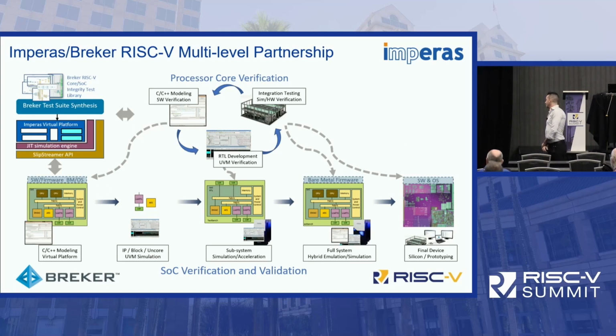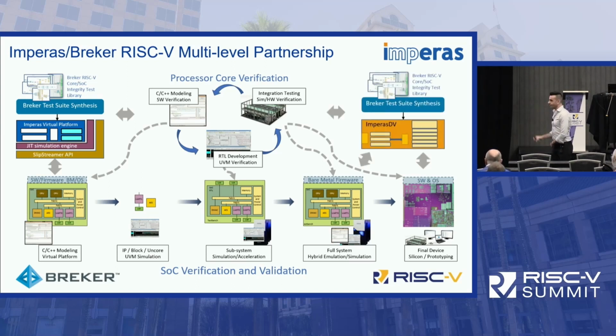This is one of the collaboration phases, and this is some experiments that we've done there. The other place where we can actually provide value from the collaboration is towards the end of the design cycle. Now, this is what you can run with RTL, with design in the loop, the actual design of the RISC-V core. You will still use the same exact test, and you will now use the Imperas processor model as your reference model. It's going to do the checking for you.